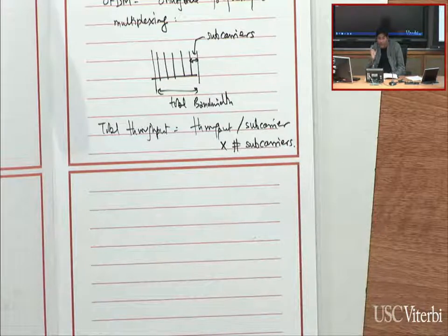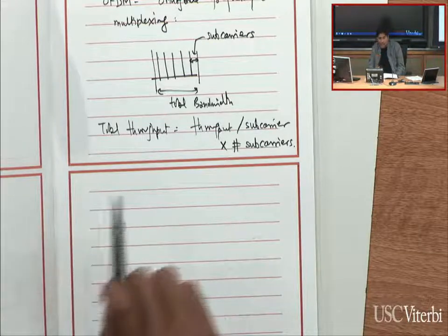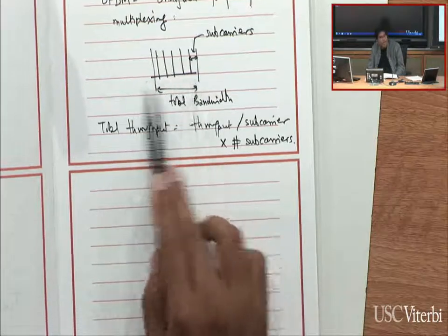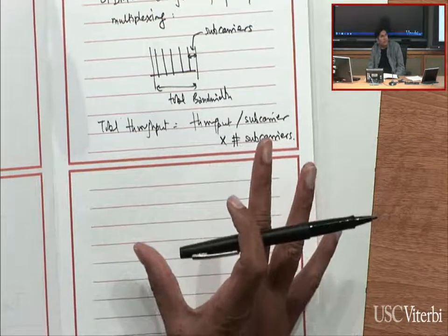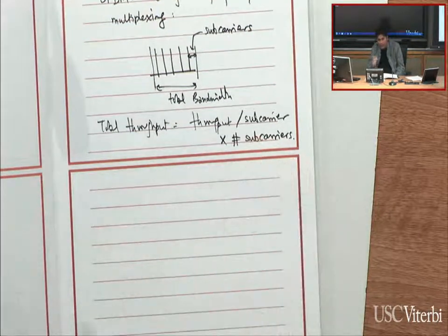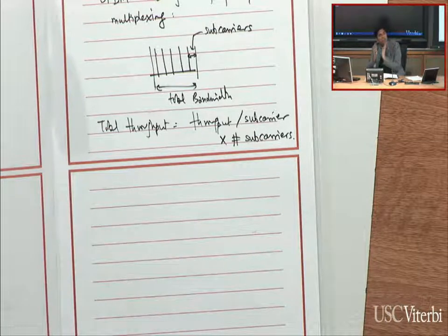So effectively, each subcarrier stream is a lower rate data stream. And we talked earlier about these channels which have intersymbol interference. If I were to send the whole thing as one high rate stream that occupies a larger bandwidth, what will happen is that those symbols will be in time so close to each other that they will start smearing into each other as the multipath reflected versions of the symbol show up.